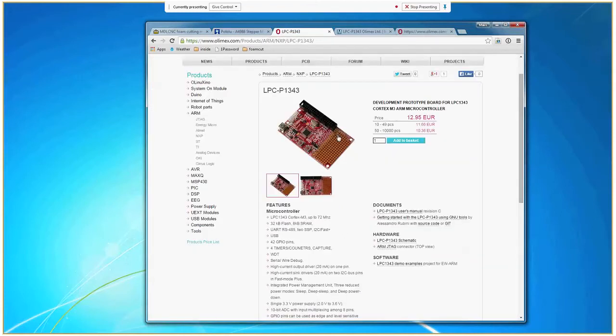The other thing, which I'm not really going to go into today, is there are also 8 digital inputs programmed in here to work as limit switches. So if you wanted to, you could have high and low limits on each of the stepper motor axes, and that would keep the motor from running up against the hard stops when they're activated. And again, that all comes out on this prototyping area, and you can connect those or not connect those depending on whether you want to use that feature.